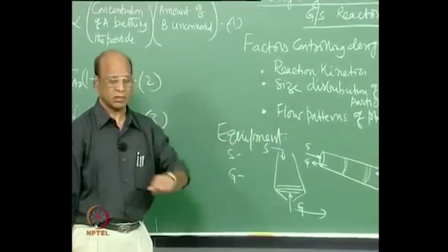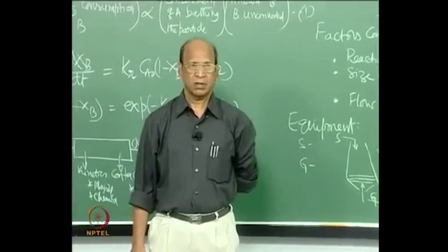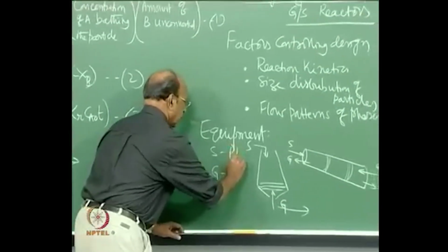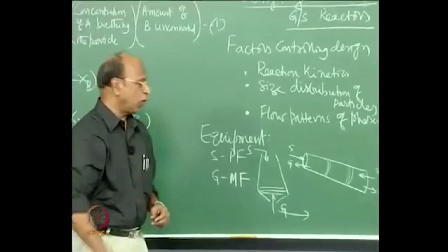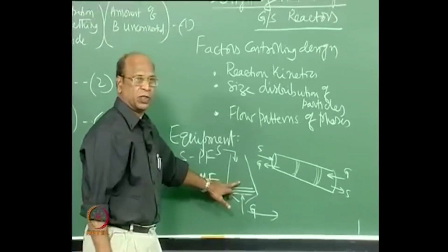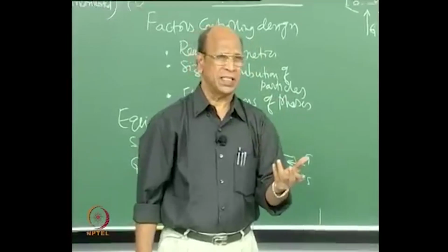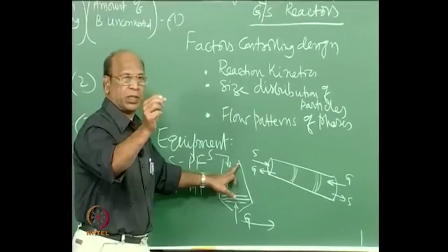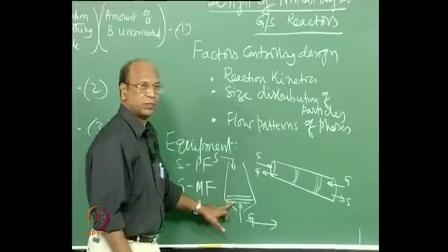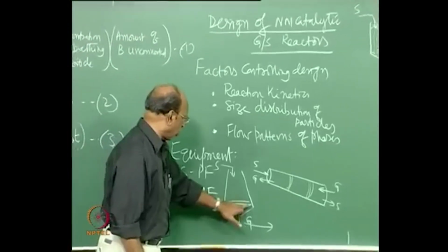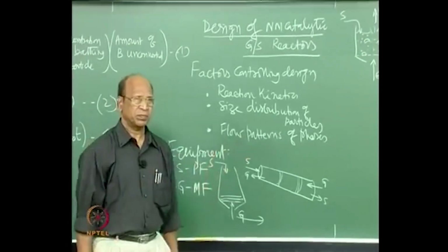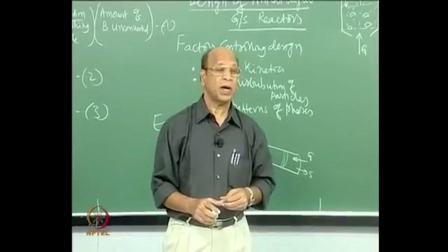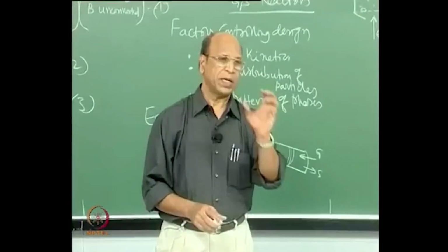Okay, gas is plug flow. So when I have mixed flow here, now understand my idea. I will tell you why you cannot use mixed flow. The reason is the definition of mixing itself. A particle which is here at any instant of time can also come here, and that particle can also go there, anytime. Is it possible in a blast furnace to have that kind of flow? Never.